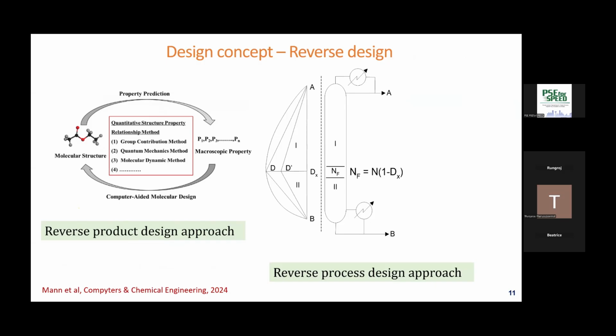On the left, you see a curve. That's the driving force curve that is calculated from the vapor-liquid phases that are in equilibrium, or in coexistence. If there is no azeotrope, then there is a well-defined maximum point of the driving force. It is known that if the driving force is large, the separation would be easy and will require less energy, because energy is needed to create the vapor and liquid.